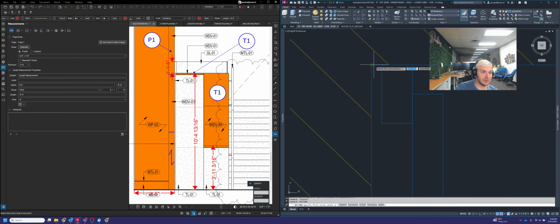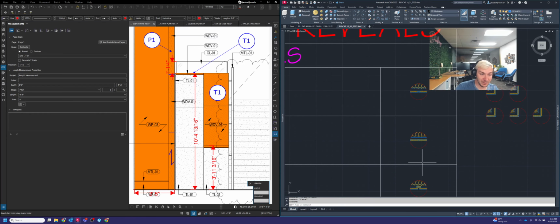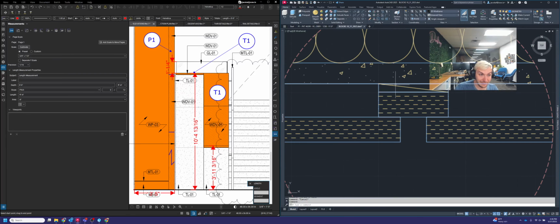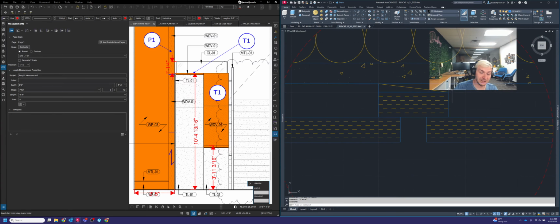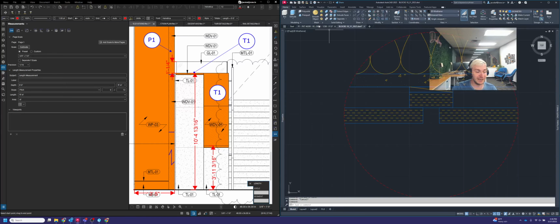Behind that full depth reveal, there is a small gap. That gap there is going to need shim. So what I'm going to do is draw a rectangle from there to there. When we go to hatch it later, it's going to look something more like this, where you have that diagonal line to represent there is shim between the wall and the back of that reveal block.